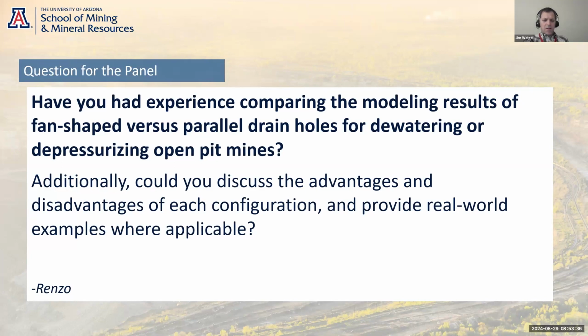The other thing too, a lot of times we're probing for unknown structures that are back behind the wall that could be holding up water. And we've had a couple instances where we hit something that pukes out 60, 70 gallons per minute for 24 hours in an active moving zone, and then shortly thereafter the moving zone starts to slow down, and it wasn't necessarily a feature that we had mapped either.